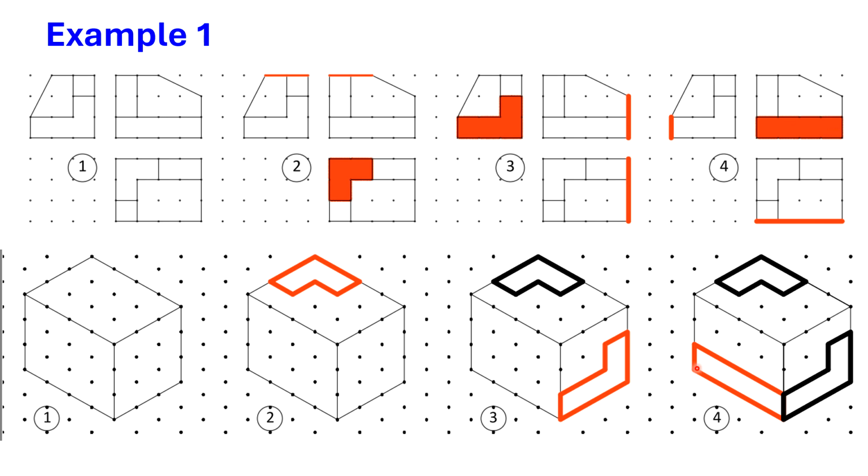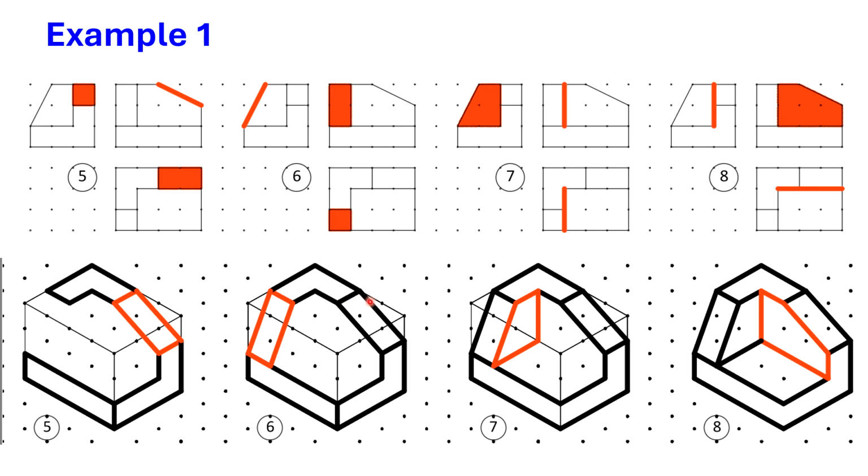So now again if you cross check, if you see the front view, this surface will be visible here, and if you see the top view, it is appearing here, and if you see the side view, it is appearing over here. So it is satisfying. So this surface's actual position is this. Then if you go to the next step, the fifth step, you have identified three principal surfaces in three different views.